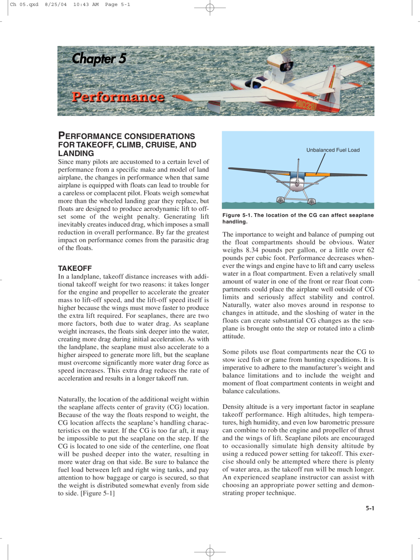For seaplanes, there are two more factors, both due to water drag. As seaplane weight increases, the floats sink deeper into the water, creating more drag during initial acceleration. As with the landplane, the seaplane must also accelerate to a higher airspeed to generate more lift, but the seaplane must overcome significantly more water drag force as speed increases. This extra drag reduces the rate of acceleration and results in a longer takeoff run.